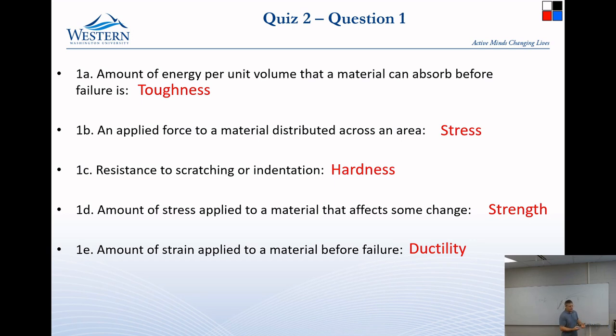It is not a material property. Ductility is the material property. Is brittleness not just a lack of ductility? Yeah, they're the inverse of each other, but you don't ever measure brittleness. People talk about it being a brittle material, but the material property that you measure is the ductility.